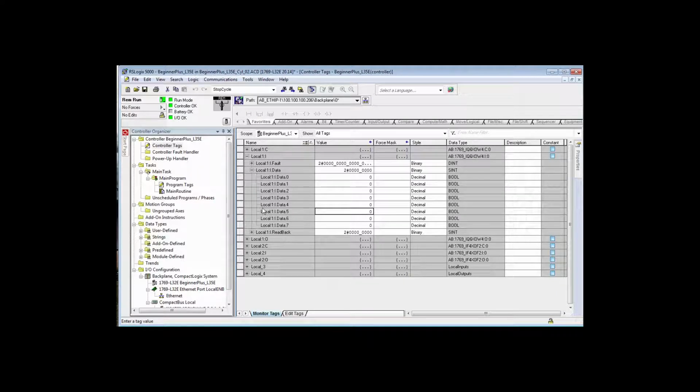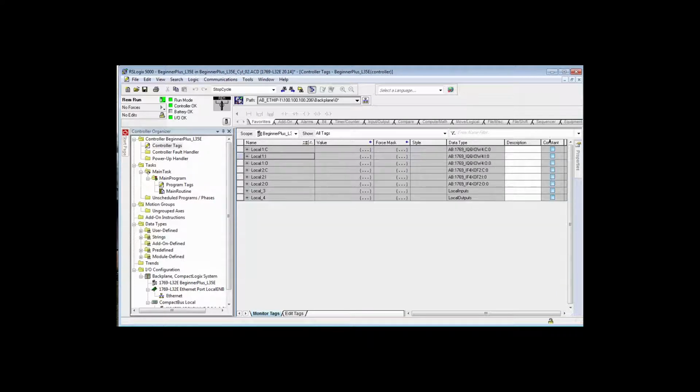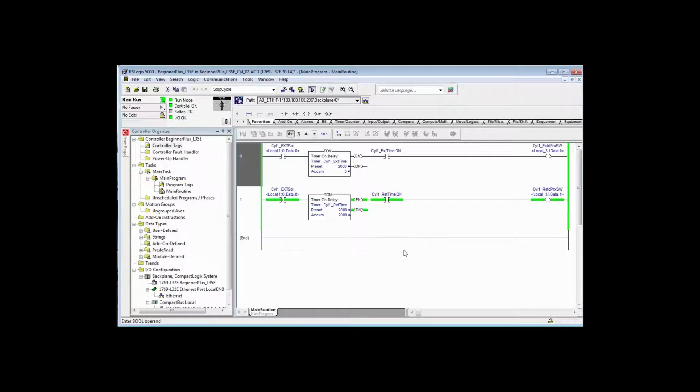Okay, so that's a little bit of review, just in case you've forgotten some of the things that we talked about in the first manual, volume 1 or beginner. This is beginner plus. Okay, here, if I energize this and I will turn on that output, I don't have logic to turn it on, because remember, this is my virtual cylinder. So when we write logic, and in our logic we energize that output to extend the cylinder, that logic will turn this bit on.